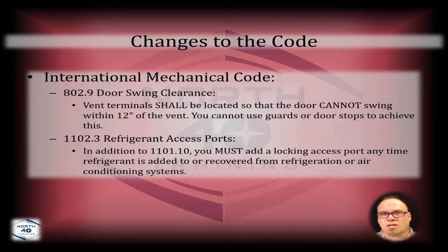If there was a privacy fence there, and I'd have to work as a person from the general public to get to that condensing unit, then I wouldn't have to put locking access port caps on there, because there is a means to keep you out of there. Okay, if it's on a rooftop, I wouldn't have to put it on there. But if it's sitting down in the alleyway where the drive-through is, I probably will have to. So now they said not everywhere.